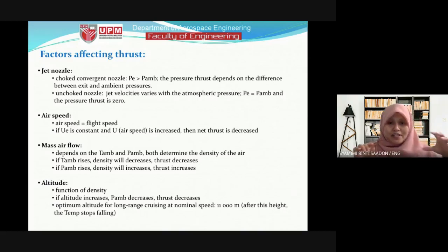At first, in the convergent part at the inlet, when we lower the back pressure, the mass flow rate and the fluid velocity increase. But at the throat, the mass flow rate will not increase anymore, even if we keep lowering the back pressure. It is like a maximum, or limited.